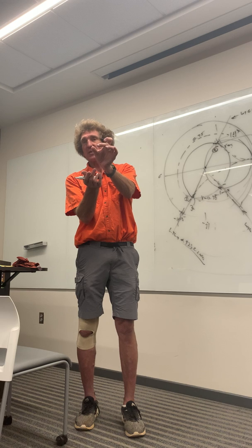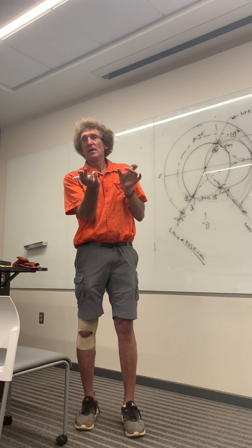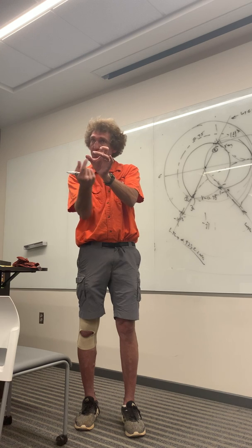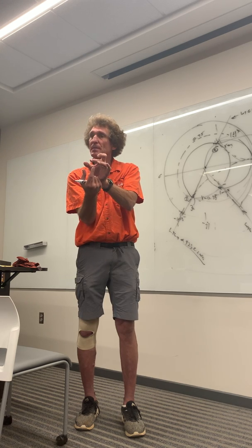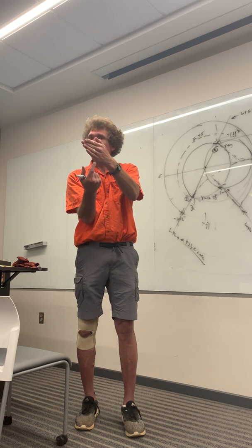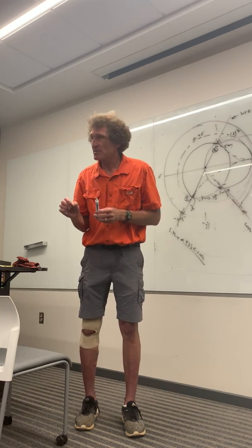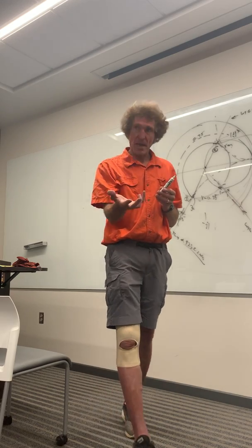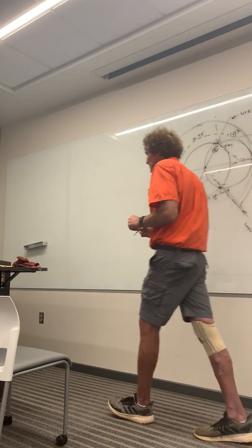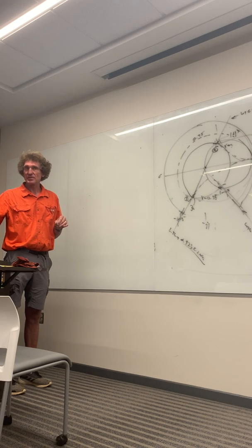Now, suppose I etch everything off, but I leave a strip of copper of a certain width on top, and right below that, another strip of copper, only that width. I etch all the other copper off. I have a transmission line. But if I put a little valley or a void between that piece of copper and the rest of the copper on the board, now I have a transmission line. You can make transmission lines on those boards by delineating a pattern, masking it, very easily, very exactly. It's amazing how accurate you can get, and how this becomes almost a trivial thing to do.